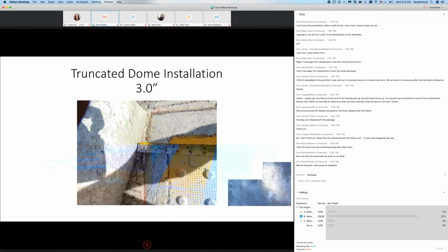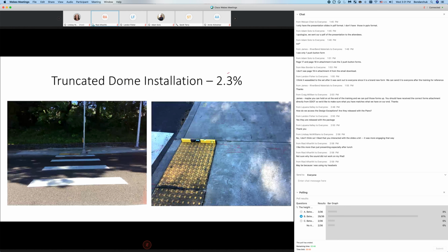So if you end up trying to press it while the concrete is wet, you end up with probably more than 2% slope. So be careful, because that part is still part of the ramp, and that 2.3% is a failure here. It should be continuous, should be the same slope, and it definitely should be less than 2%.